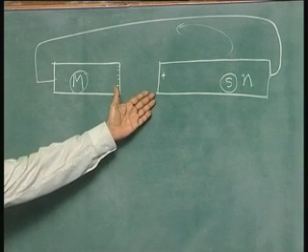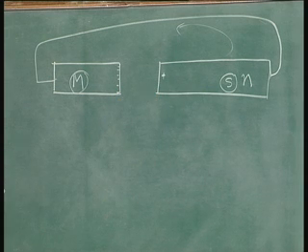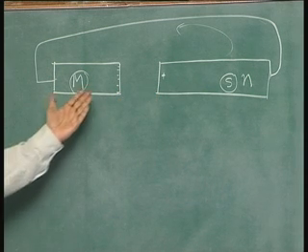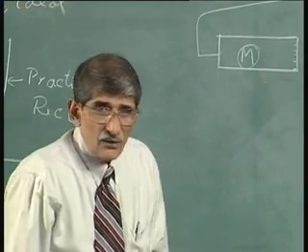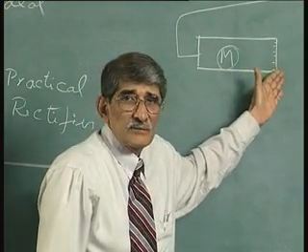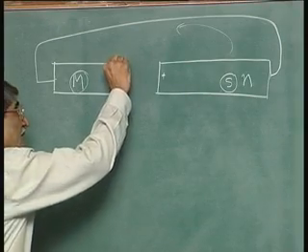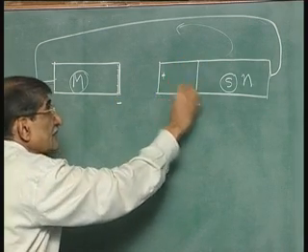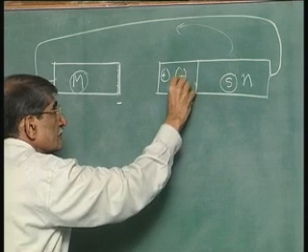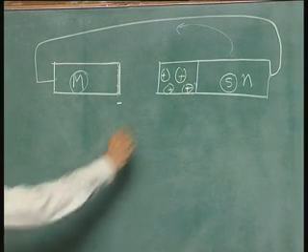The number of electrons, or the doping concentration, in the N region is 10 to the power of 15, 16. Here the electron concentration in the metal is 10 to the power of 22 and above. So if you put in a few electrons here, it is not going to occupy space, it will be just a monolayer that will give that negative charge. So you have negative charge here. The net positive charge will come from a finite width. So there will be a depletion layer.